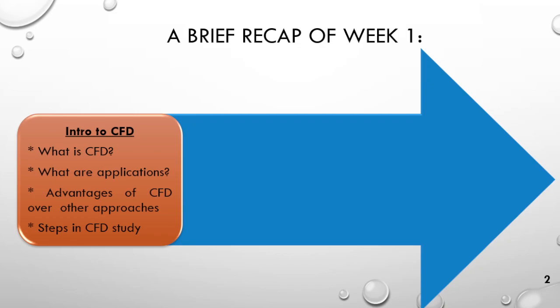And if you have an air and water interface, like waves splashing on the surface of some stone, you have to go for multi-phase modeling wherein you have air also and water also. Okay, so that is again a different physics. So you have to identify the physics first, and define the governing equations for that particular physics. That is the first thing.